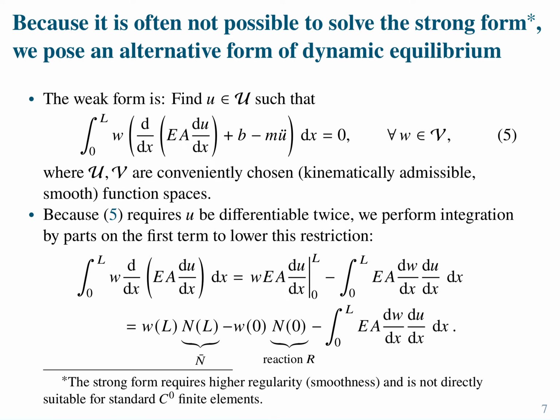Well, and someone may ask, why not the Dirichlet boundary condition? Well, it's also the Dirichlet boundary condition, because what is the force at a point where you're prescribing the displacement? How do you call that? The reaction, right? So you have the reaction popping up.